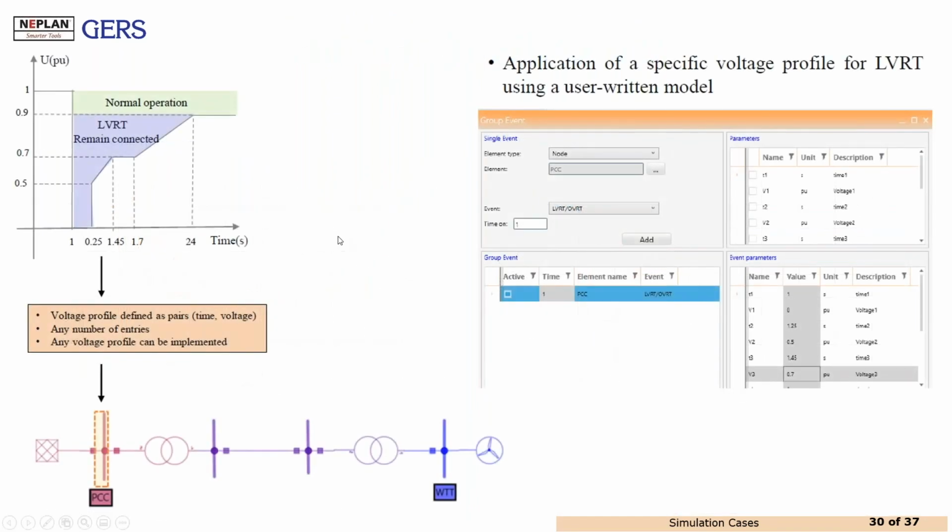The other simulation that I presented here is the specification of specific low voltage ride-through profiles. In this case, what we did was to define a low voltage ride-through event, and we validated the system performance during the dynamic simulation.